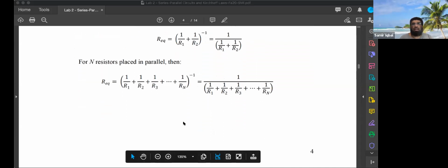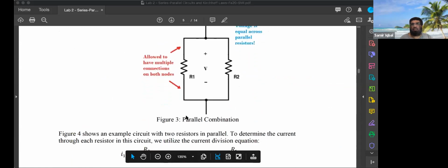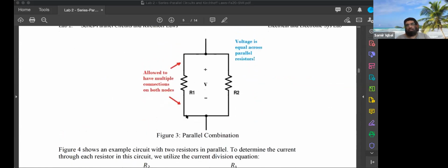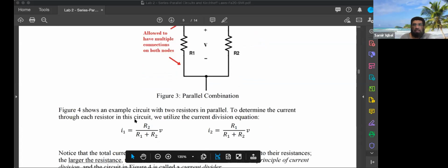All right. In this case, the voltage is the same, but the current gets divided. So the current is found in a similar way, by ratio and proportion, taking the proportion of the resistance. But in this case, the current I1 depends on the ratio with respect to the other resistance, so current 1 will be divided with respect to resistance 2.